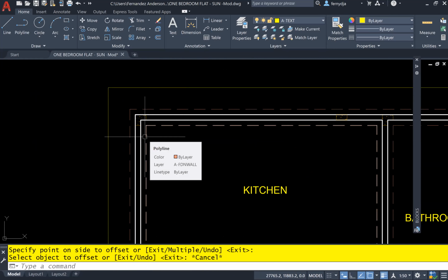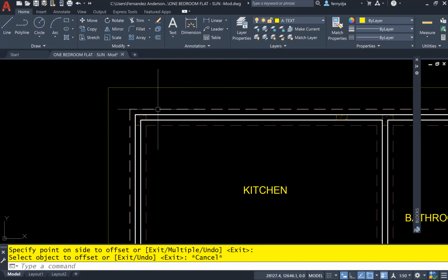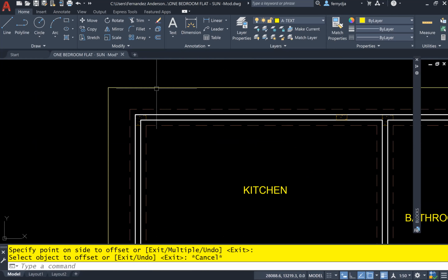Remember, the baseline feature only works between lines, and there is no line down here, dimension line. So we can't work with baseline for line 1. So we use linear and continue to finish up, and then baseline for line 2. So that's what we're going to do now.